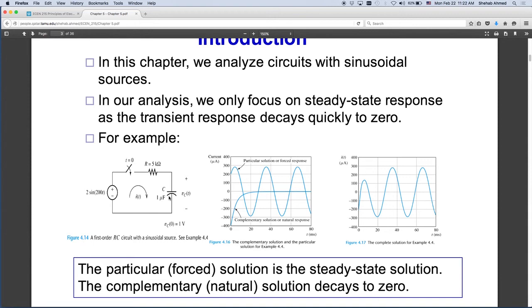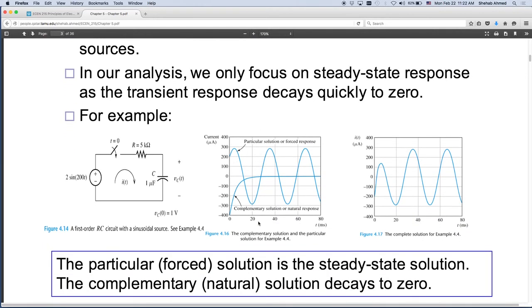What's going to happen? The charge that was stored in the capacitor will flow in this RC circuit, and after a certain number of time constants, decay to zero. Right? It has a certain voltage, then the voltage will drop to zero. Right? And that's what you see here. So this is the current waveform, due to the fact that you had initial charge on the capacitor, and you connected a resistor across that capacitor, for example.